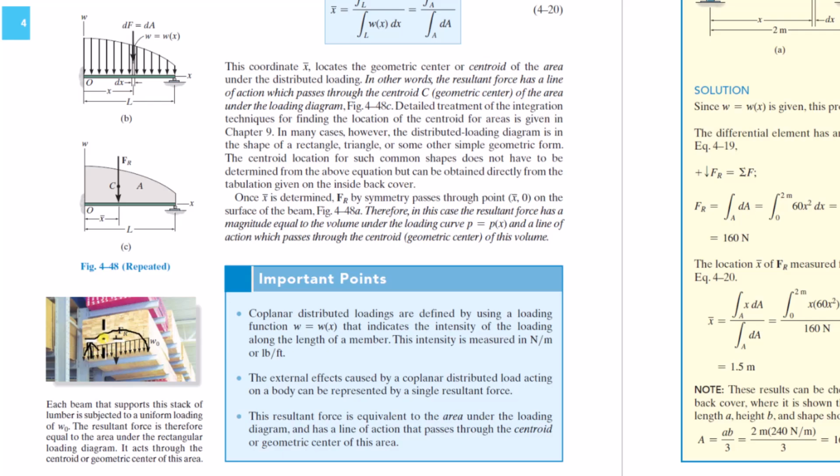That's really what the load distribution is like. If you have a block of steel laying on the ground, and the mass is uniformly distributed, and it's perfectly flat at the bottom, and the ground is perfectly flat, it's not a uniform distribution. It's something like this. Right at the middle, the load is higher, and then towards the edges, the load is lower. But a uniform distribution should be perfectly fine.